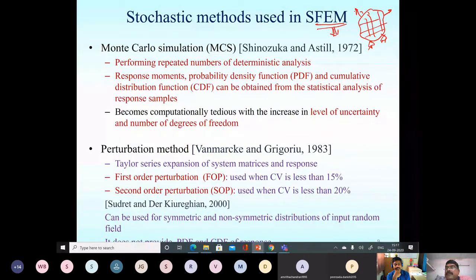If you look at elasticity, which you might have studied, you will end up with equilibrium equations and boundary conditions, with different essential boundary or traction boundary conditions. Since it is a boundary value problem and the governing differential equation is valid for the entire region, if I take a small region, it should be valid for that region as well, and so I can solve it for that region. That is basically the concept of FEM.